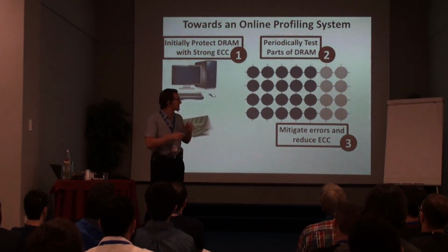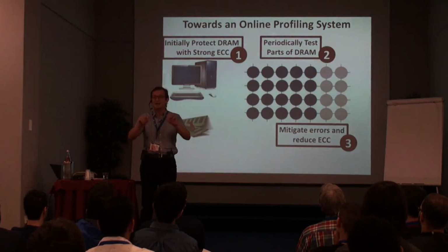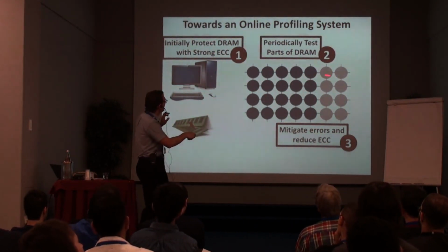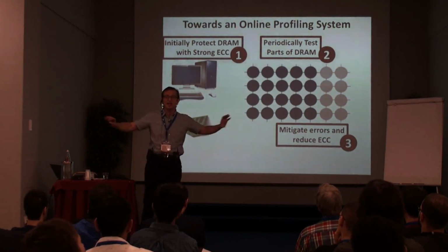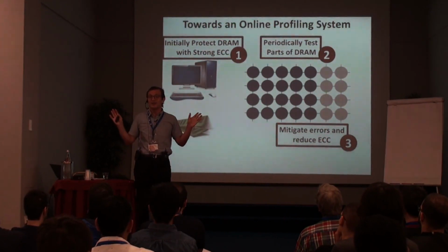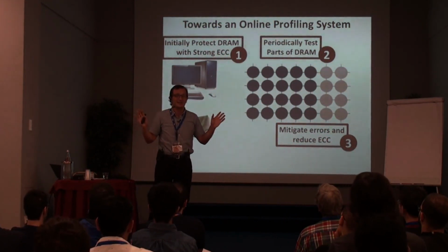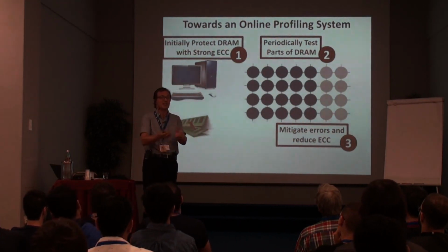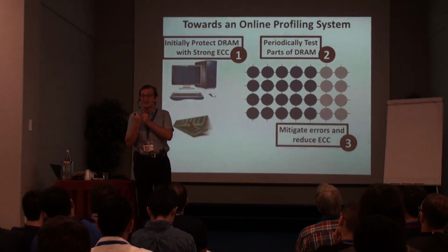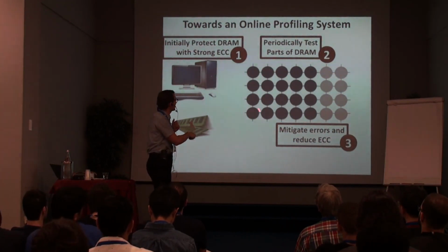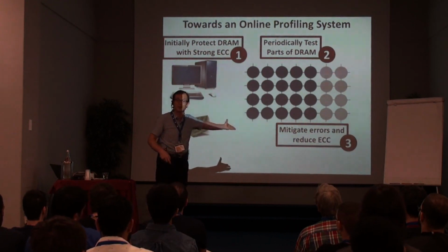I'll give you another example. This is data pattern dependent, right? If you know the data pattern in DRAM, for example, if all of the cells are discharged and all of the cells around them are discharged, maybe you don't need to refresh DRAM at all, right? In that case, if you know the data. Even though you need that data, you don't need to refresh it because you know that charge is not going to leak from there. So that's very powerful if you can exploit that, the knowledge of what the content over here is. Then you don't need error correcting codes as well, right?